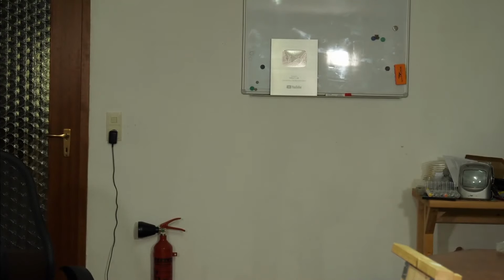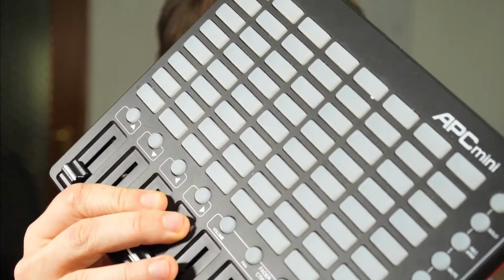I have mixers, launch pads, like these ones and these ones. They are recognized, and I got all the input from them to my ESP32. But for a device like this, I have to check. There is this negotiation and descriptors that you have to analyze when the device connects on the USB, to get everything right and pick the right endpoint to communicate with. There needs to be some logic, so I will implement this progressively.